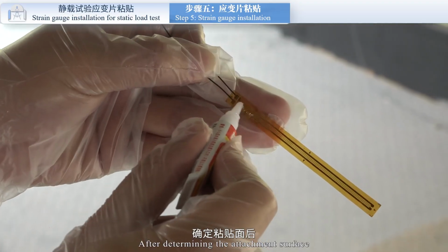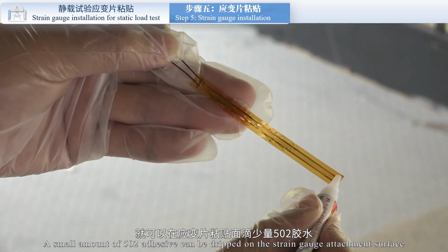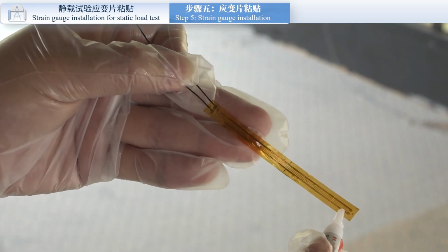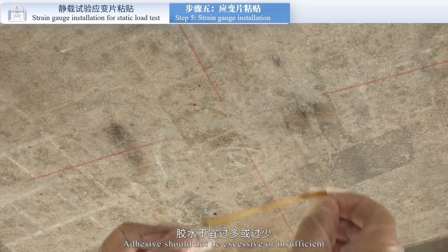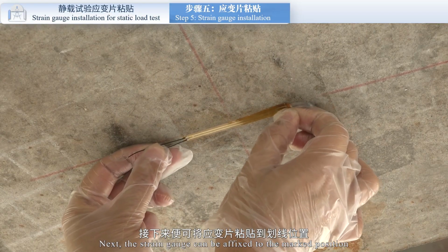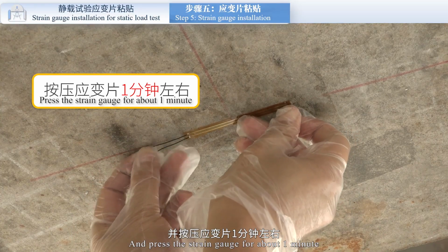After determining the attachment surface, a small amount of 502 adhesive can be dripped on the strain gauge attachment surface. Adhesive should not be excessive or insufficient. Next, the strain gauge can be affixed to the marked position and pressed for about 1 minute.